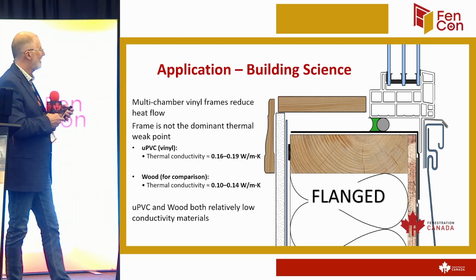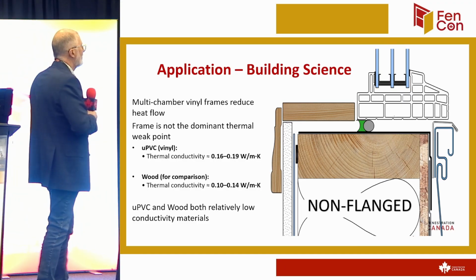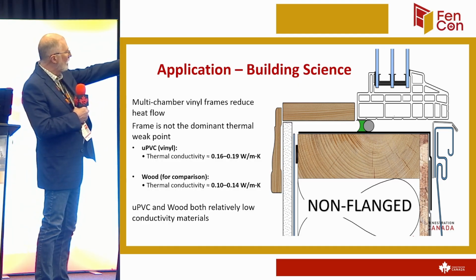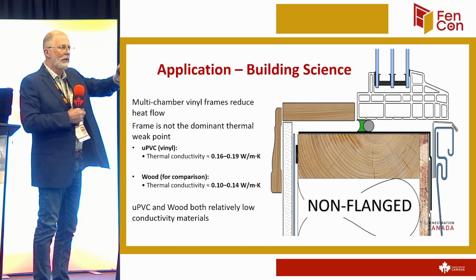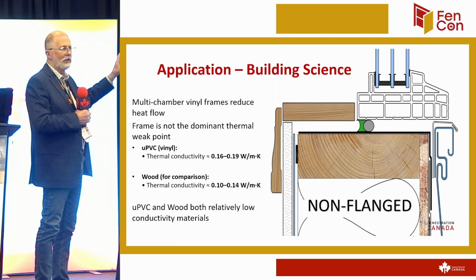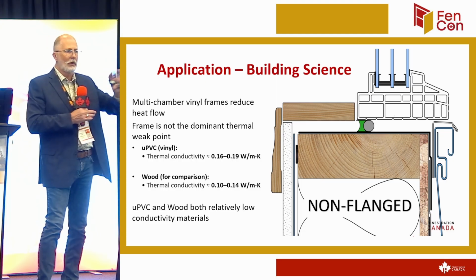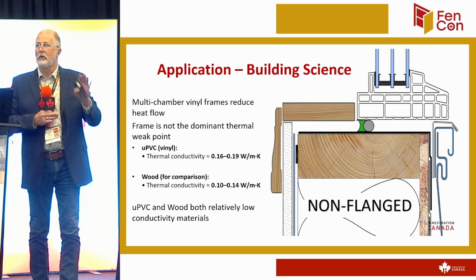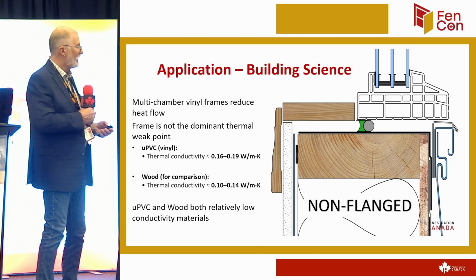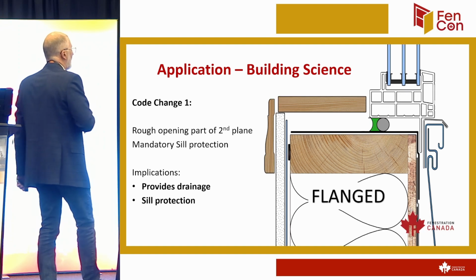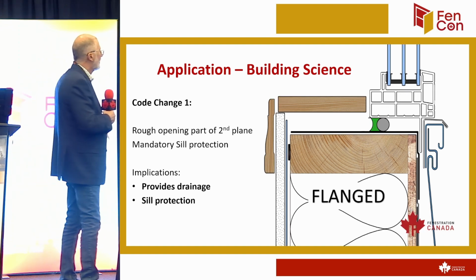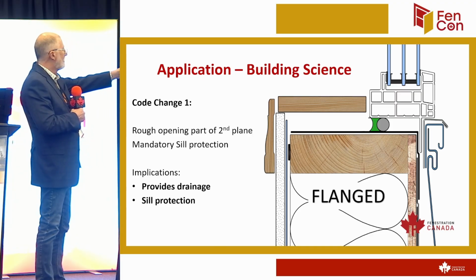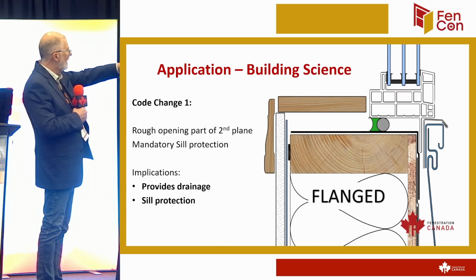influencing the surface temperature. So whether that's a flanged window or a non-flanged window, again, when you look at the non-flanged window, it looks like there's tons of room for air to blow in there. But again, remember the compartmentalization aspect of that. It's never going to be perfectly airtight, but if it's 80 or 90%, you've still got that moderated pressure differential between inside and outside.